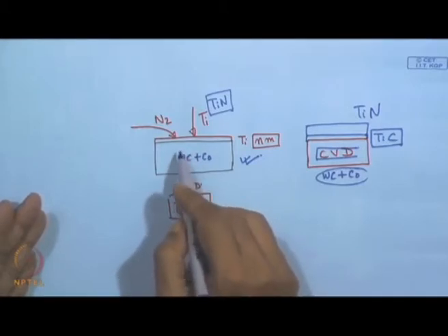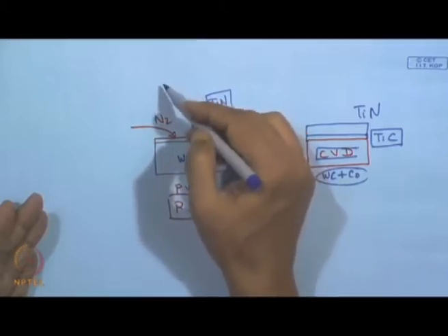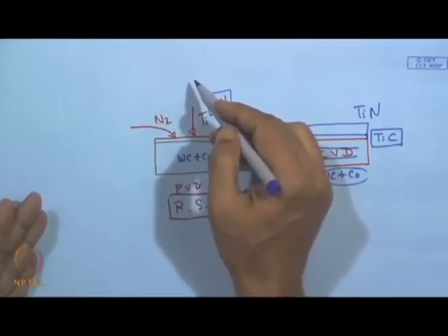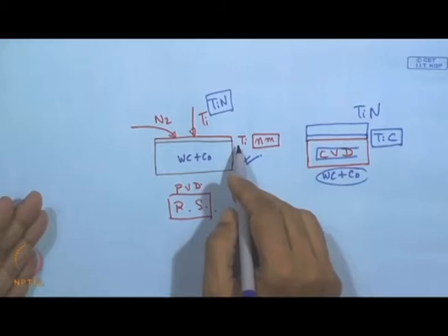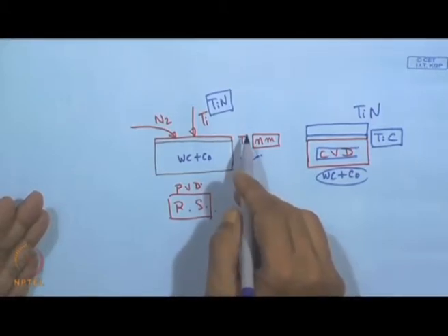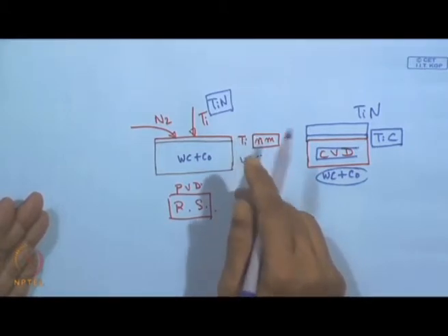So, in this interface cleaning, first is target cleaning on the target side, then using that target material for cleaning the substrate material, then using that target material for a nanometer level coating, which is an adhesive layer, and then finally switching over from this adhesive metal layer to the layer of nitride of that particular element. So we can find at least 4 steps in getting this coating, and in the 4th step the titanium nitride coating, or any nitride of a metal coating, takes place.